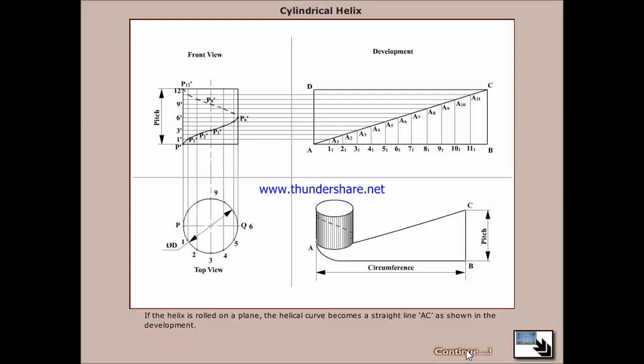Now, if the helix is rolled on a plane, the helical curve becomes a straight line AC as shown in the figure in the development.